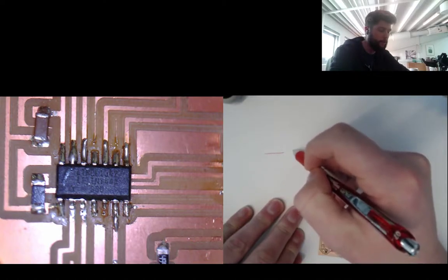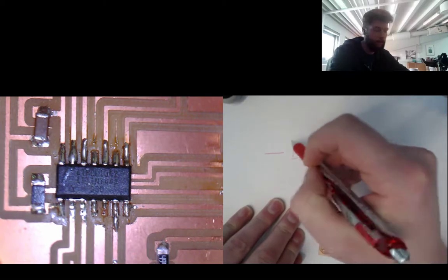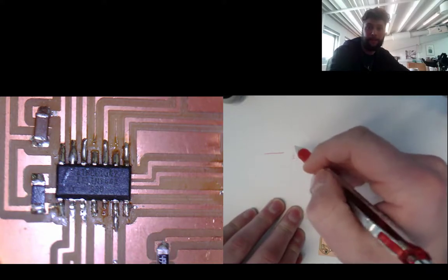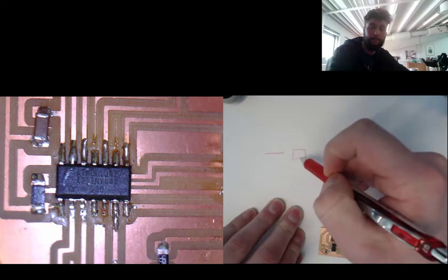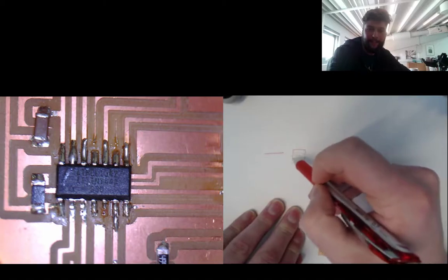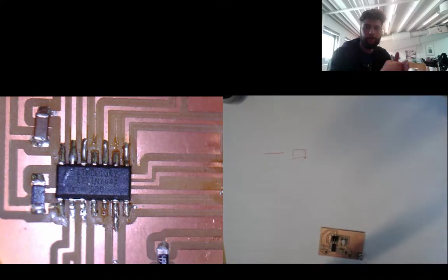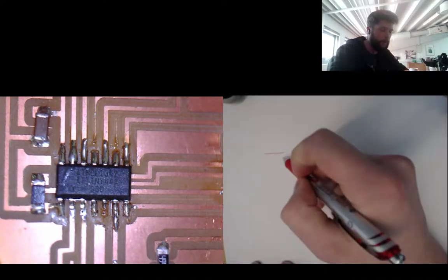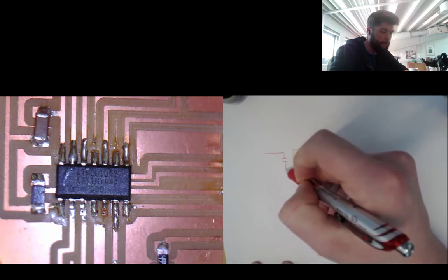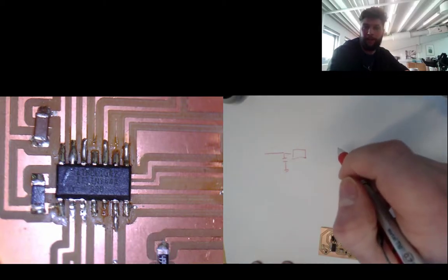It's going into the box, and in the box there's processing going on, and the processing requires different amounts of current. It requires different amounts of electrons at any given time. Because the electrons at this tiny level have a little momentum, they have some push, you know. So the capacitor that is leading from the voltage in to ground is basically working as a little siphon.